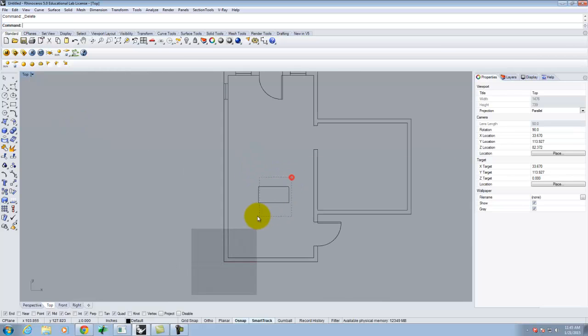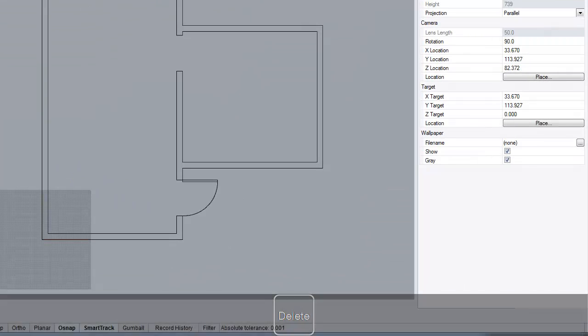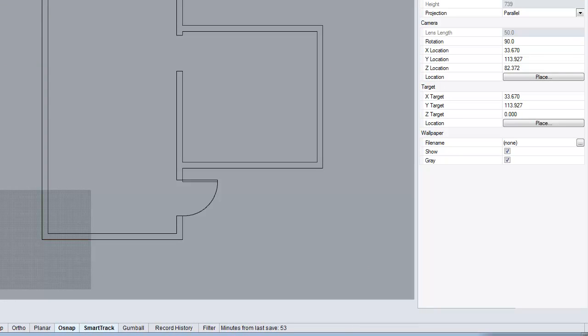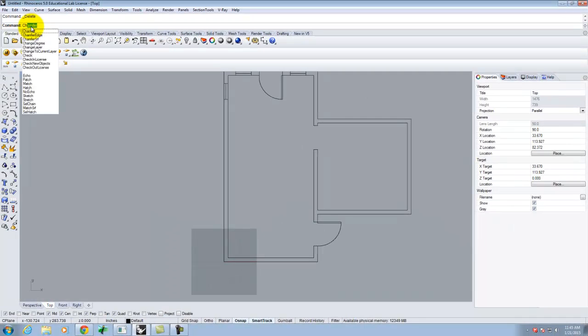Okay. The other thing that Rhino does is, and this does involve remembering what the name of the command would be, but if you think, oh, I wanted to chamfer something, if you start to type chamfer, it'll give you all of the options that are similar to chamfer, which is a great way of finding something if you're looking for it.